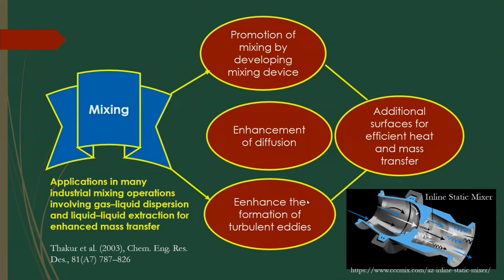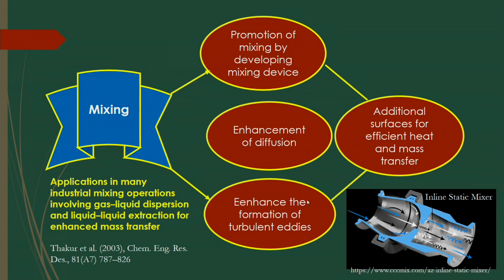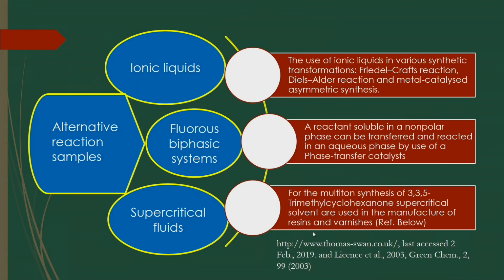Also another phenomenon is called mixing, the promotion of mixing by developing mixing devices. You have to improve the device to intensify the mixing of the fluid. In that case you can get enhancement of diffusion, and you can get more turbulent eddies whenever the turbulence of the fluid mixing is generated by that particular design of the devices. Even additional surface you can get based on that fluid mixing, which will give you efficient heat and mass transfer for that particular operation.